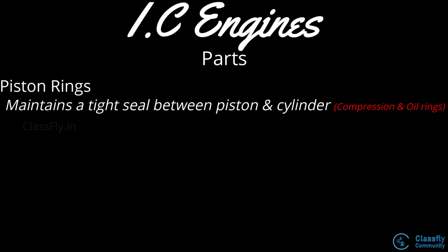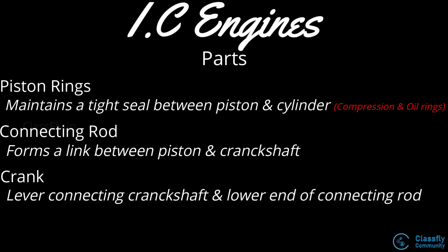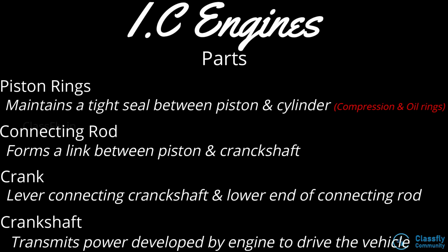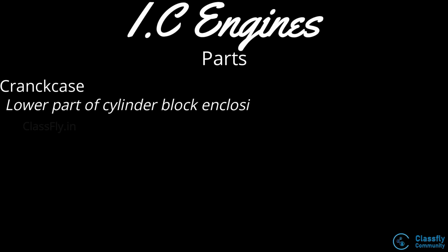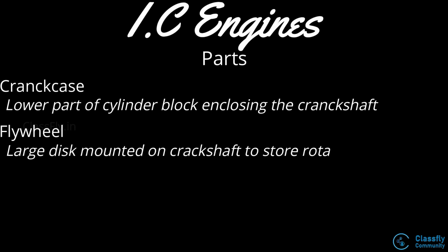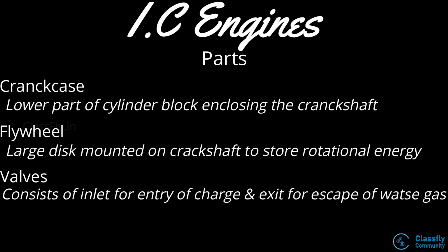piston rings, which are used to maintain a tight seal between the piston and the cylinder, the connecting rod, which forms a link between the piston and the crankshaft, the crank, which is a lever connected to the lower end of the connecting rod, and the crankshaft, which is used to transmit power developed by the engine to drive the vehicle, the crankcase, which is the lower part of the cylinder block which encloses the crankshaft, and also the flywheel, which is a large disc or wheel mounted on the crankshaft which stores rotational energy, and then the engine valves, which are the inlet and exhaust valves, used for the entry of fresh air or fuel and also for the exit of the burnt gases.